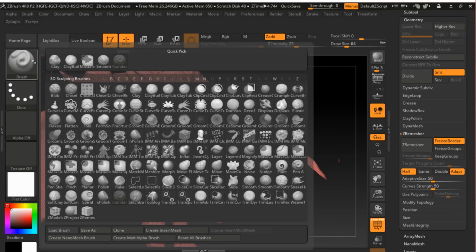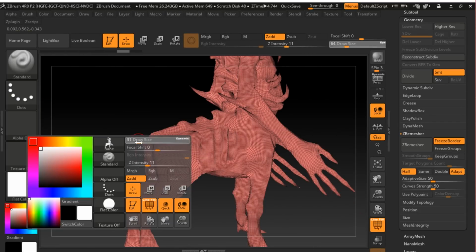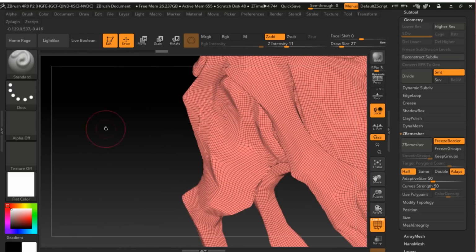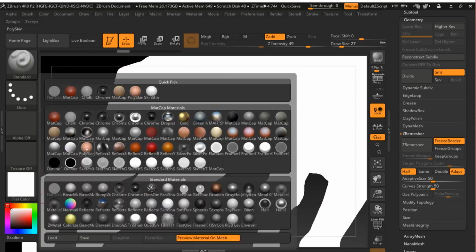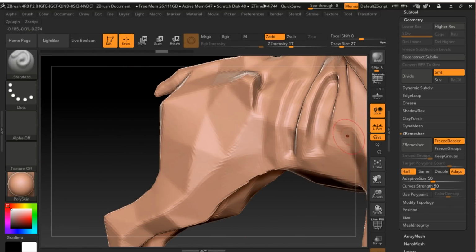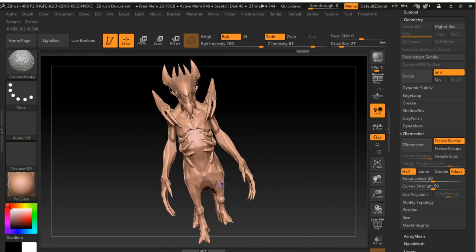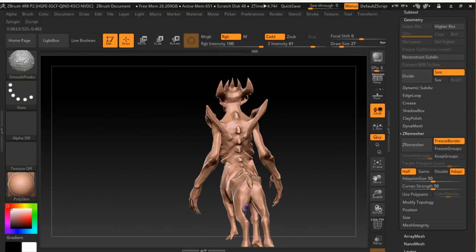Once thin areas are identified, we need to selectively thicken just those areas while avoiding poofing out the entire model and losing the sharpness of our overall geometry. We'll do this by alternating between a smoothing brush and an inflate brush. For definitions of what needs to be fixed, the best resource is the Shapeways Materials Information page.